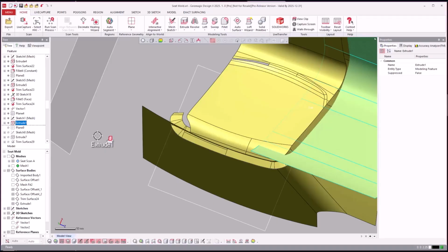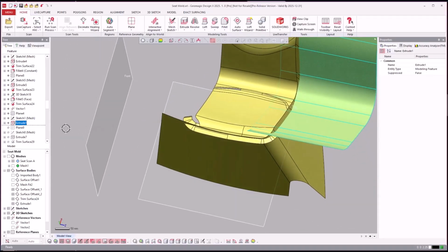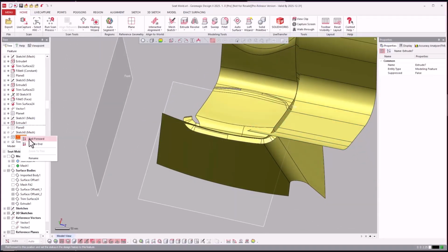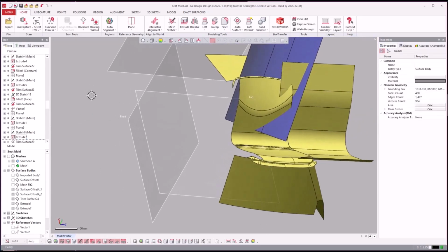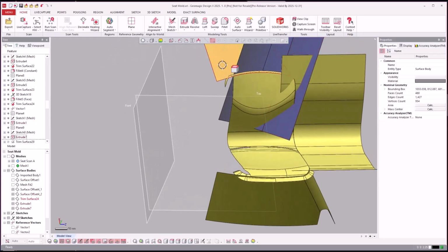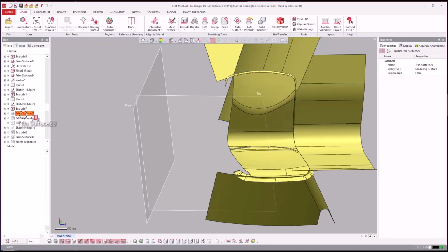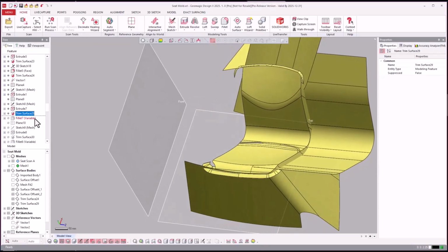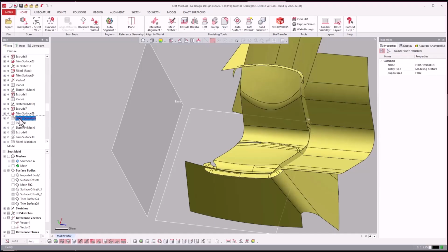Now we're going to trim from this direction. Trim from that top direction. Again, all of this is going to form another band of a trim around the border, is really where we're going with this. See that? So we're going to trim all these pieces together and work our way around the outside. And you see that we filleted that together.